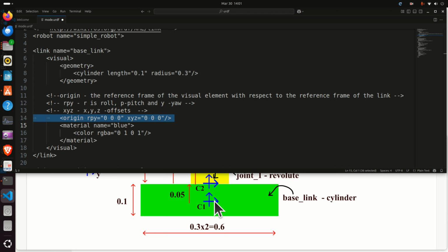That is the joint that is completely attached to the ground and doesn't move. This is a fictitious joint that's used to simulate the robot and to have the absolute reference. And over here, we need to define the location of the coordinate system attached to the center of our link with respect to that fictitious or fixed coordinate system.